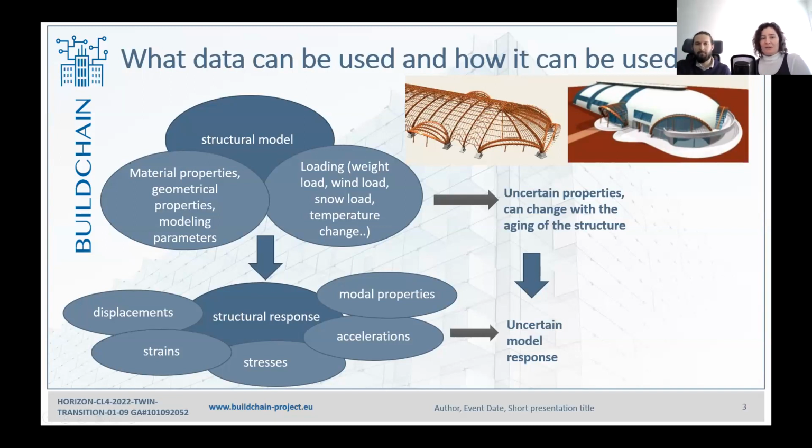Sorry, just a minute. Let me switch on the pointer. So this is an architectural plan of a building, and we don't need the whole building. We only need the load-bearing parts, load-bearing elements of the building. So this is what a structural engineer would need. And all the rest we need just as information of the weight on these load-bearing elements.